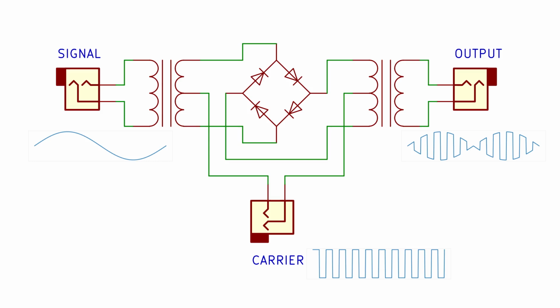If you take a look at the frequency content of the output, what you find is that none of the frequencies present in the original signal or carrier are present in the output. Instead, what's in the output is sums and differences of the signal and carrier frequencies. And that adds up to a complicated set of frequencies, leading to a complex and interesting sound. So that is the ring modulator, with ring there referring to that ring of diodes you keep complaining about.